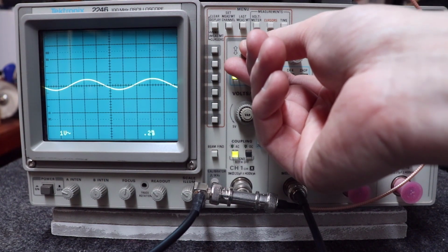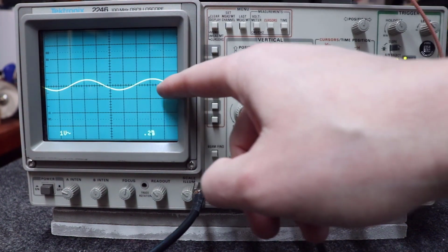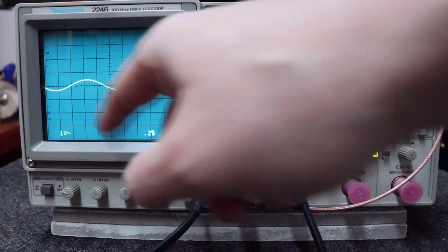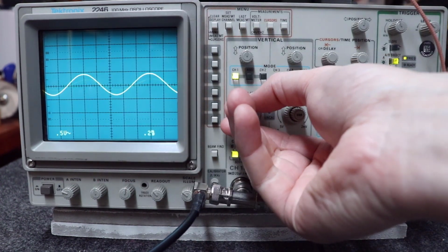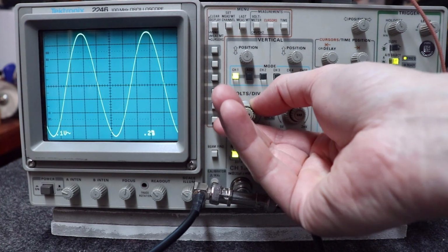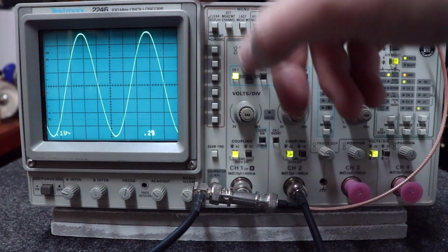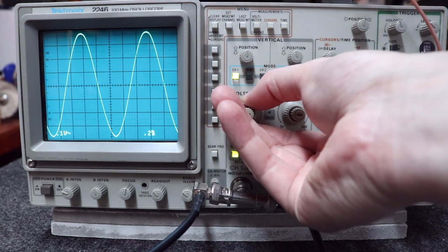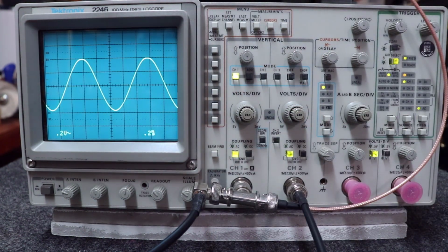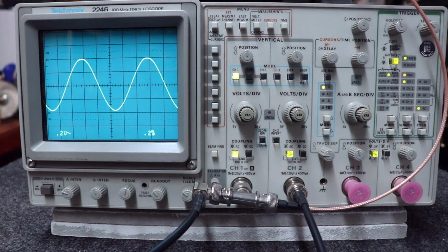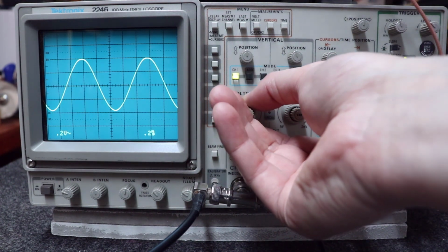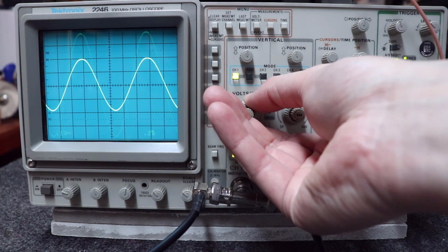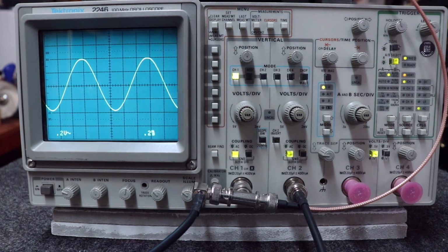If you put it dead in the middle, then you could kind of know that is the center line of your signal here. And by the way, it's kind of hard to work with a signal like that, right? I like to get my signal on up there, so I'm using a lot of the screen here. You don't want to get it too far, though, that you're starting to go off screen, top and bottom. So something like that right there might be a good place to be at, okay? So I'm varying my measurement here, not the signal, the same exact signal in both of these scenarios, okay?